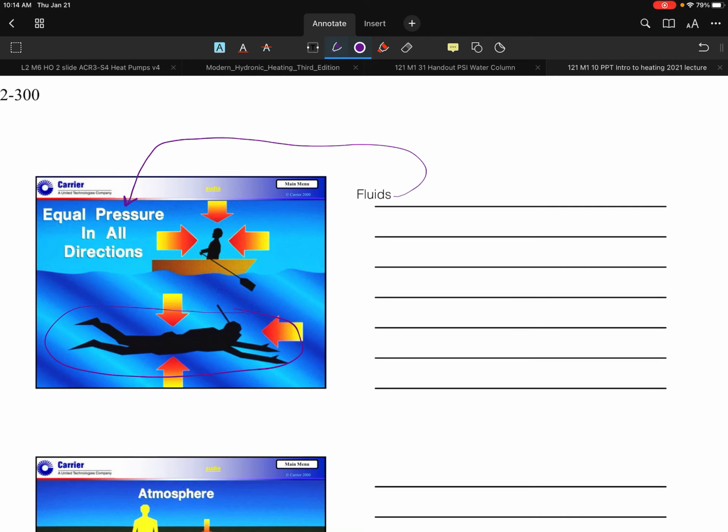There are ratios that we use in our industry for water. For example, every time there's a level of fluid of approximately 34 feet, that will be equivalent to approximately 15 psi. It's equivalent to atmospheric pressure. A little bit about that as a rough idea. I'll talk more about that later, when we're dealing with pressures.